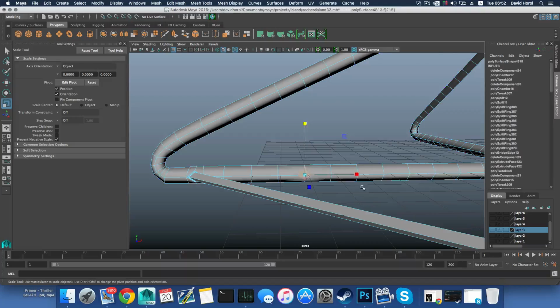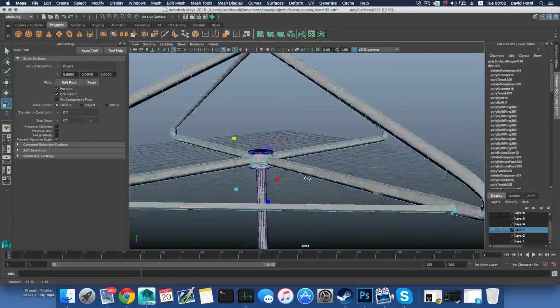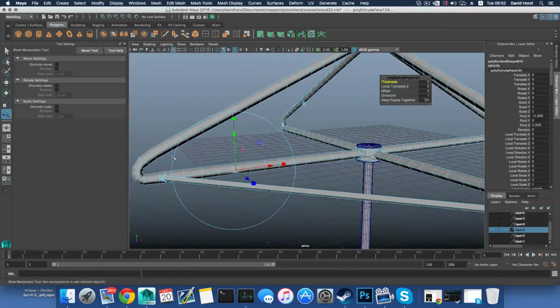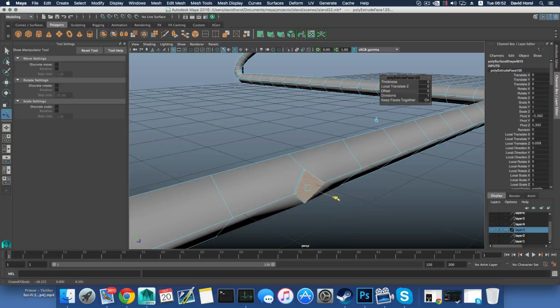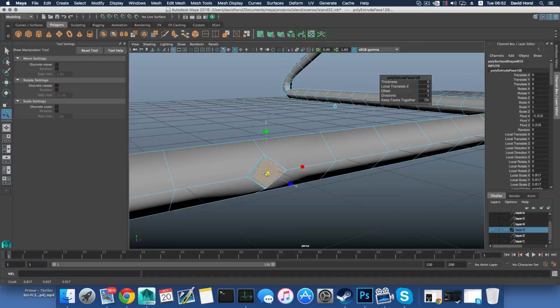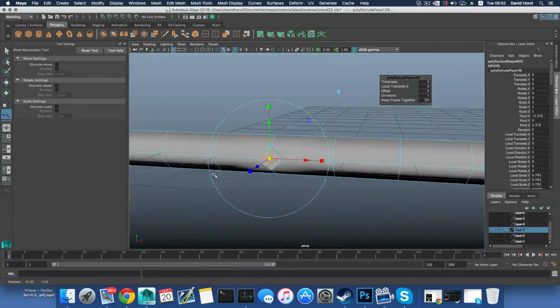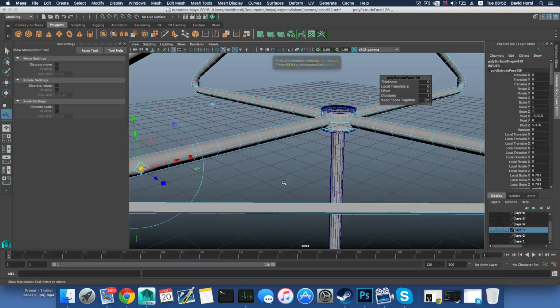Okay, let's grab this face, let's grab this face, let's extrude them once. I hope that they are the same scale, but anyway, extrude this out, extrude this again, bring this like so. Let's have a look. That's okay. Press F8 to bring it back to object mode.